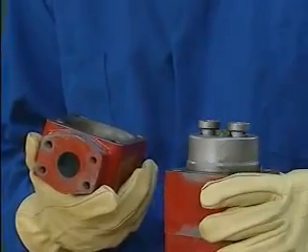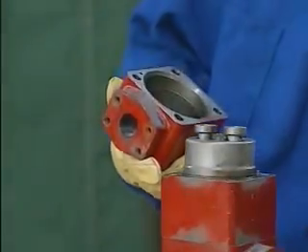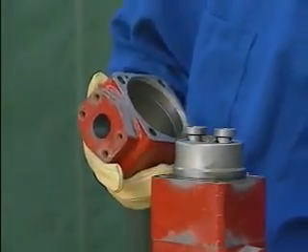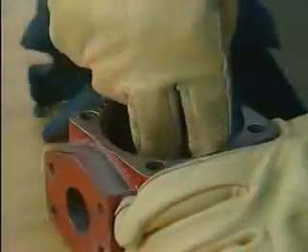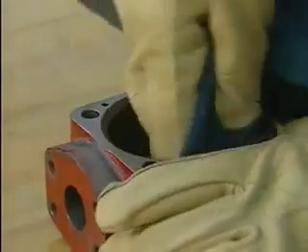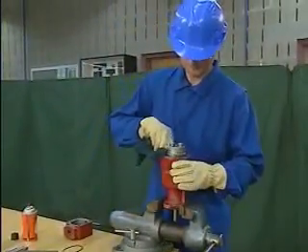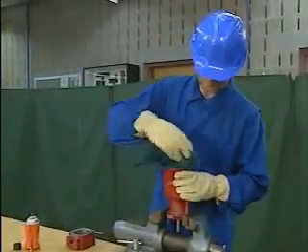The process of installing an O-ring is similar to the process for installing a flat gasket. Let's look at an example of an O-ring installation to see how it can be done. In this example, a mechanic is sealing part of a casing for an oil pump using an O-ring. To start, the mechanic cleans the flange faces and the raised sleeve on the flange that the O-ring fits around.